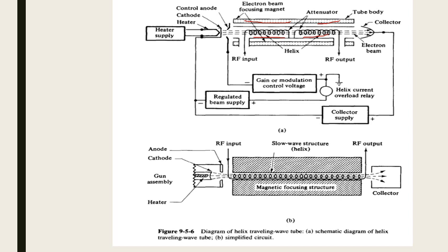And remember, these are O type tubes. O type of tubes means the electron beam and your RF velocities are trying to move in the same linear path. This is a cathode supply. We are having different voltages. We are trying to control the amount of energy that will be generated. Please note that the gain generated by this was 60 dB. How do you think it came to 60 dB? By increasing the length of the tube, you can increase the gain of the amplifier.